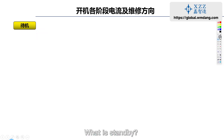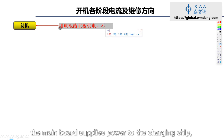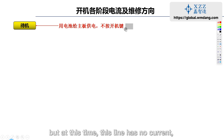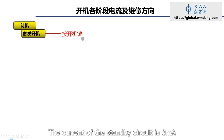What is standby? It is to use the battery to supply power to the mainboard without pressing the power button. The mainboard supplies power to the charging chip, converts it into the main power supply, and then supplies it to the power supply chip. But at this time, the line has no current, which is called the standby circuit. The current of the standby circuit is 0 milliamperes.